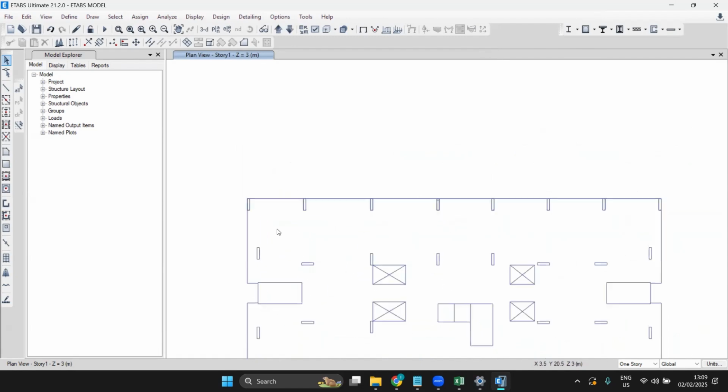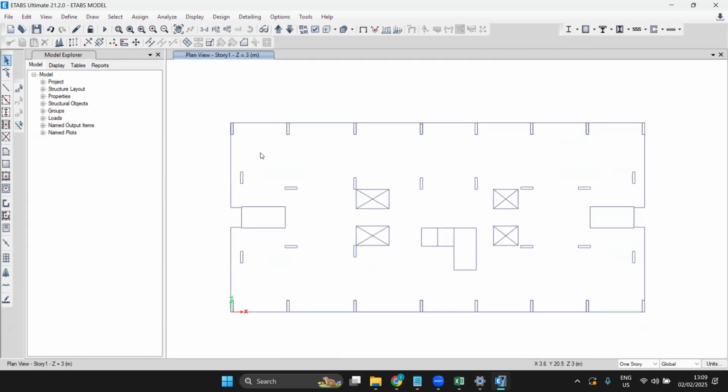When you explode, how do you convert it into a polygon again? Control. So we have to select the region, P edit. You go to P edit, right? Yes, P edit. Then select it, and you can join the line. It will become a polygon again. So P edit.